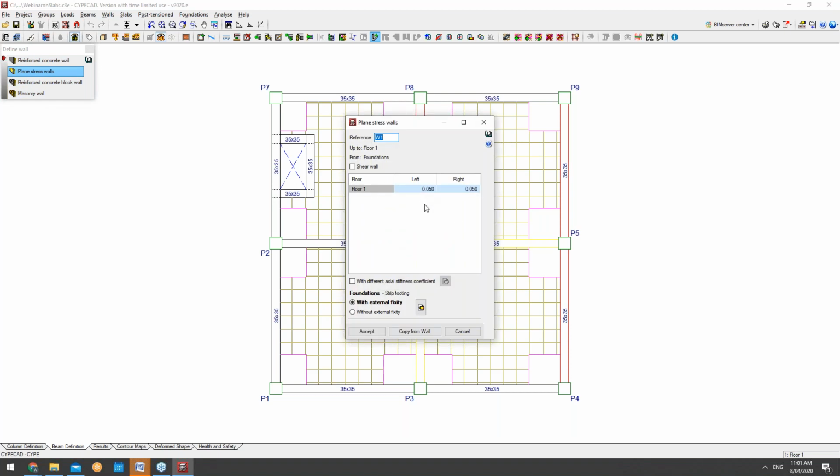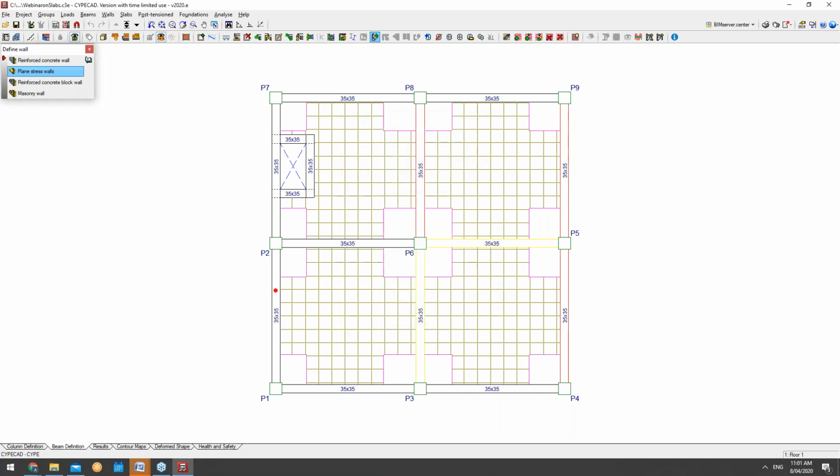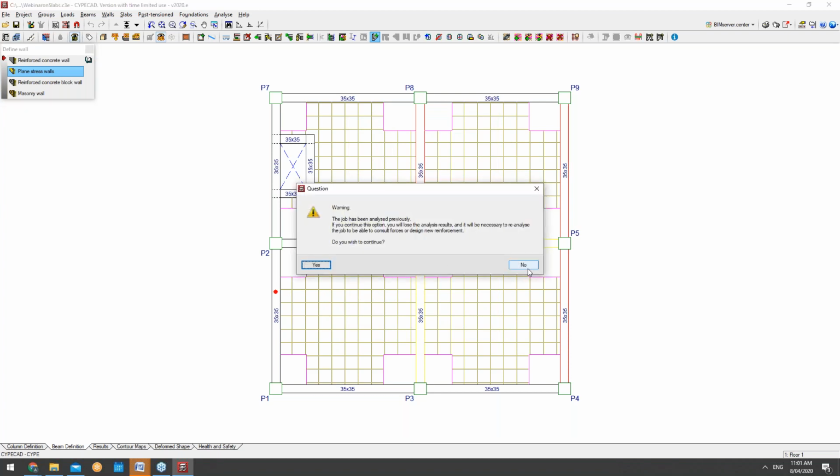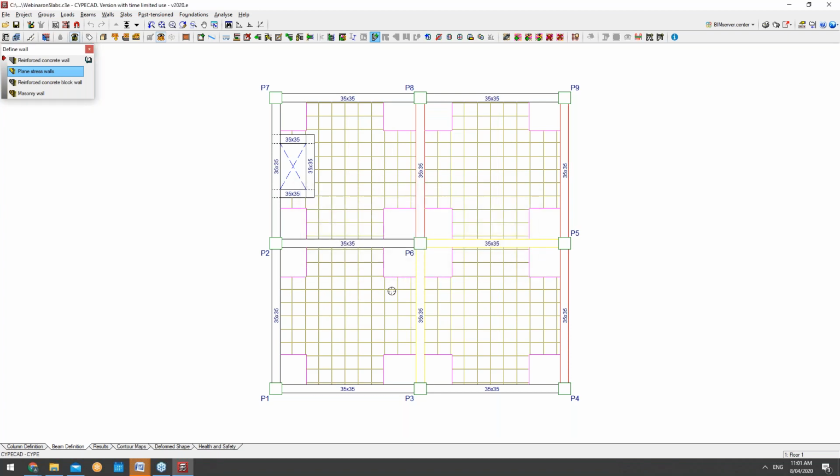So upon introducing these walls, of course, those loads will be attributed to the certain location that you specify them, and you'll be able to see those loads once I insert the particular wall. So once I do generate those partition walls, those specifications and those loads will be attributed to the slab. I hope that answers your questions. And of course, they will be taken into the design with the analysis as well.